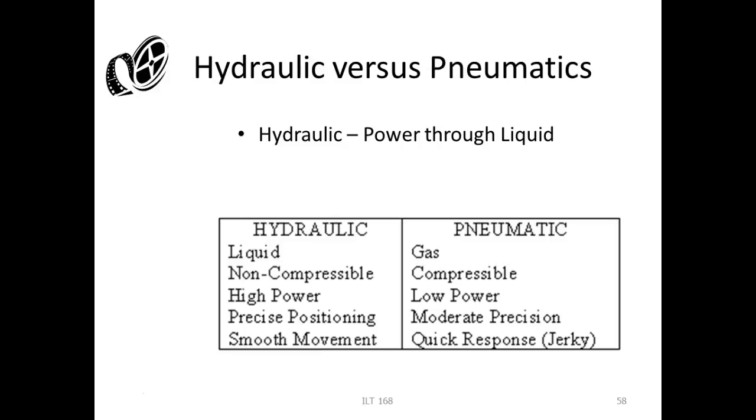So pneumatics is very, very cheap to install because just about all your tubing is plastic tubing. You don't see very much metal tubing in pneumatics. We run a lot lower pressures, which means it's safe. With hydraulics, you can literally shoot that oil through your skin. I think I told you about it in the Navy when we got the shot.